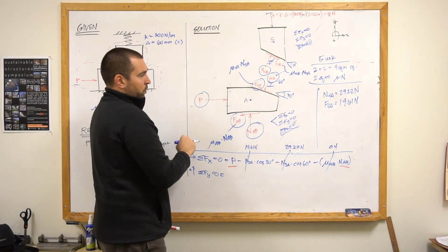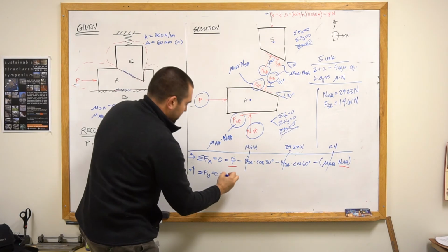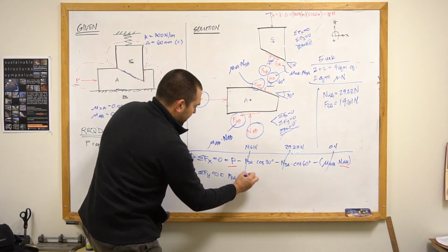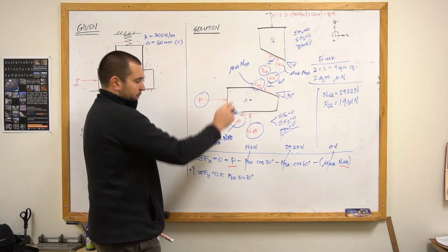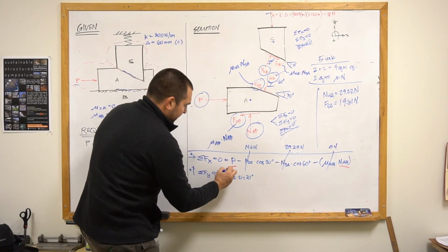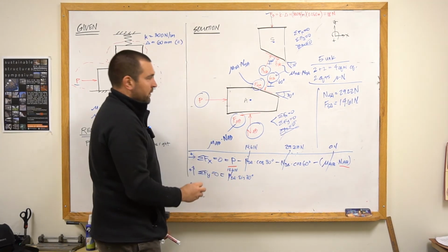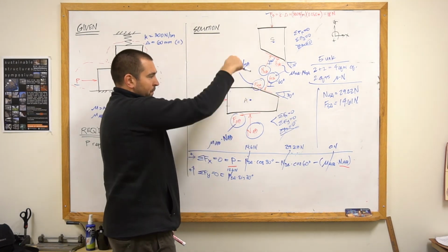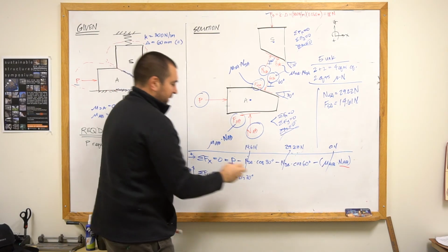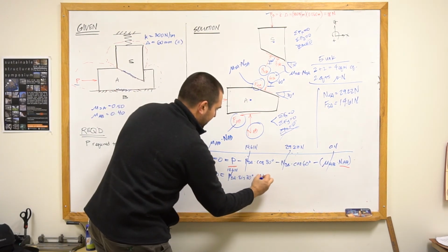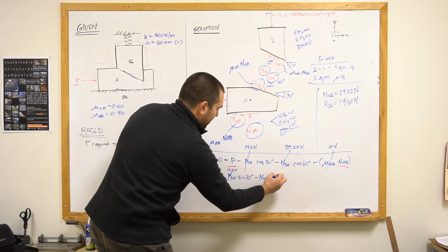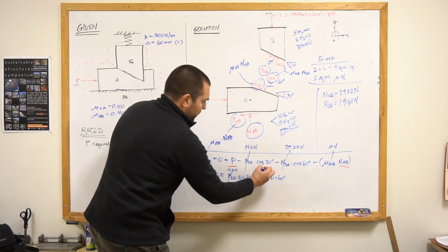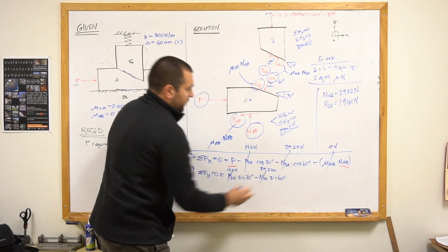The vertical component would be times sine 30. So it's FSA times sine of 30 degrees. Just like before, I know what FSA is. In this case, it's 14.61 newtons. NSA is going downwards, but it's inclined. The vertical component will be sine of 60. So I get minus NSA times sine of 60 degrees, but we know that NSA equals 29.22 newtons.